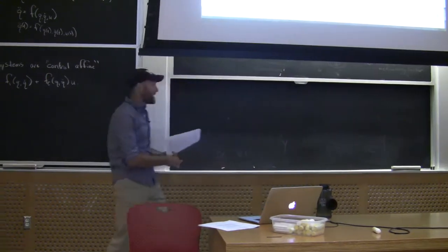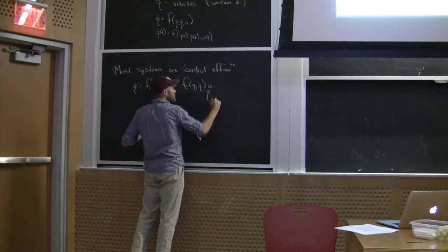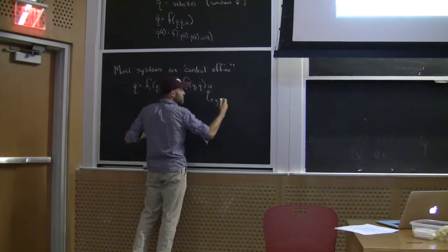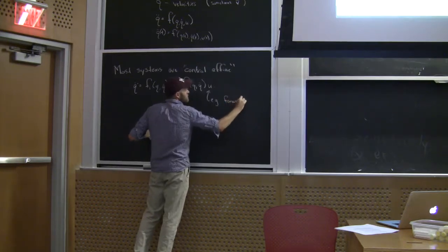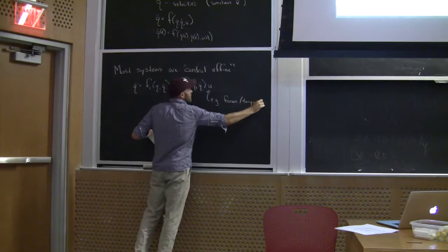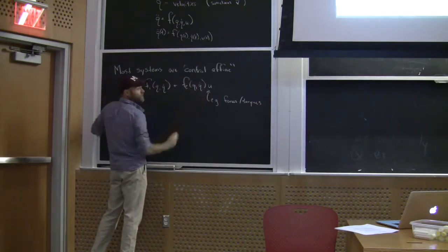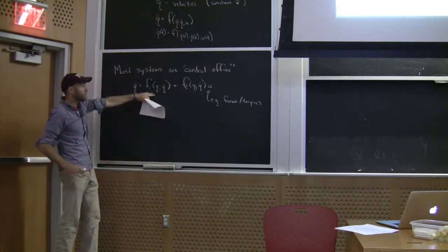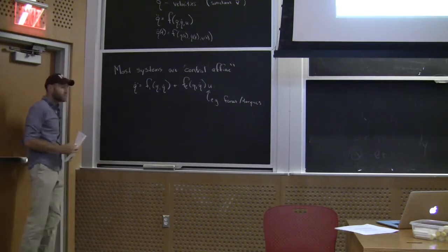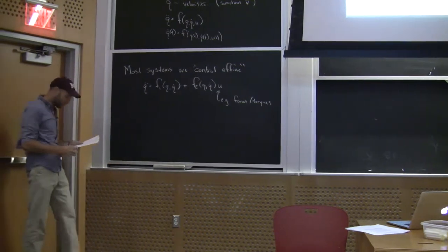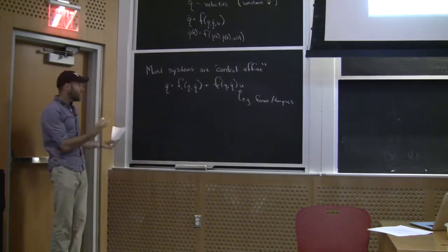And that's really just saying F equals ma again. So if my control inputs are torques from a motor or forces from some motor, then my accelerations are affine in those forces, right? So I might have some contributions from gravity, okay, but apart from that, if I put in more force, I get more acceleration, right? In a linear way. Okay, this is enough structure.